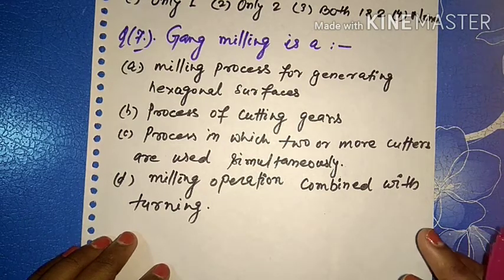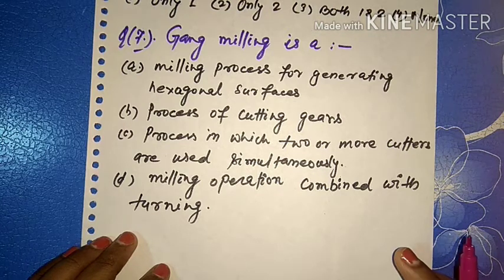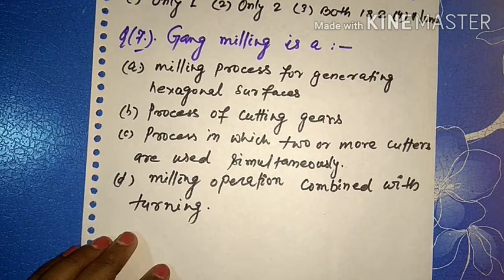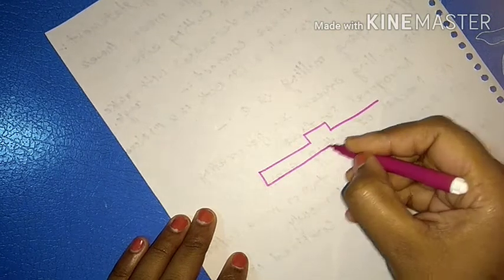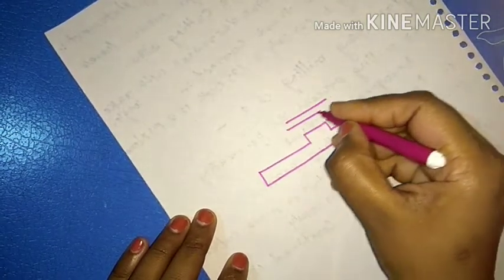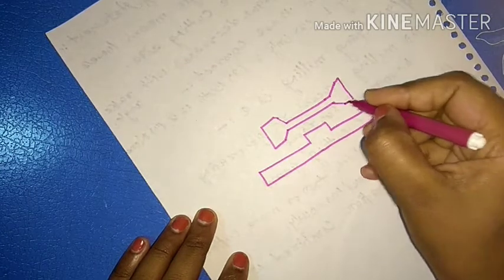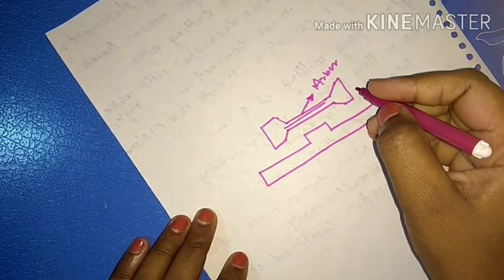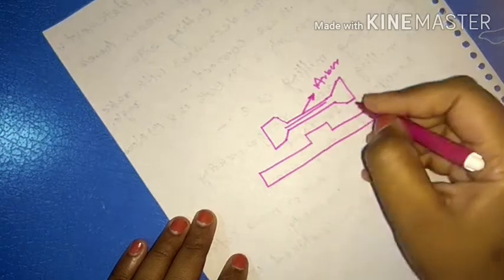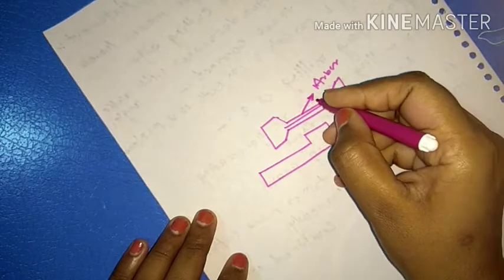स्ट्रेडल मिलिंग में 2 साइड्स मिलिंग कटर आर माउंटेड विथ ए डिजायर्ड डिस्टेंस बिटवीन देम सो दैट बोथ साइड ऑफ ए वर्क पीस कैन बी मिल्ड साइमल्टेनियसली. कहने का मतलब है अगर हम इसको इस तरह से दिखाएं, स्ट्रेडल जो मेरा मिलिंग होता है वो इस तरह से होगा. ये जो मेरा होगा ये अर्बर होगा. ये क्या है? मेरा अर्बर है, ARBOR अर्बर. सो इन स्ट्रेडल मिलिंग 2 sides milling cutters are mounted with a desired distance between them so that both sides of a workpiece can be milled simultaneously.